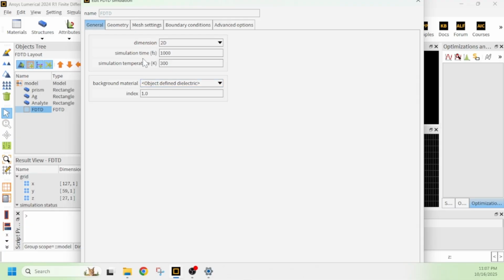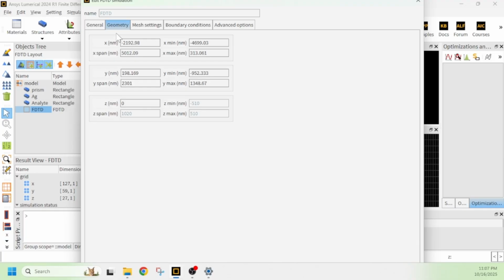Here is the final geometry. Now I am going to set this geometry, and the FDTD x-range can be -500 to 1000, and the other value can be -1.25 to 1.25. Since this is 2D FDTD, the z-axis will be disabled here.